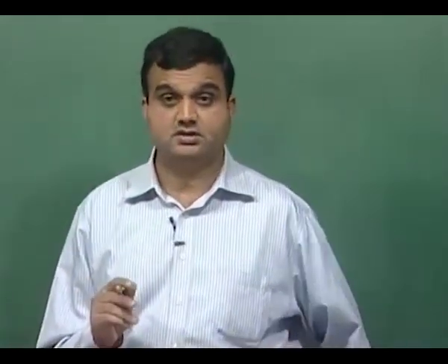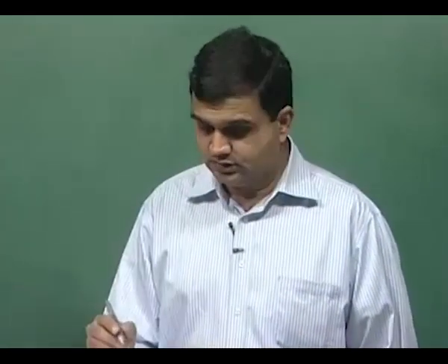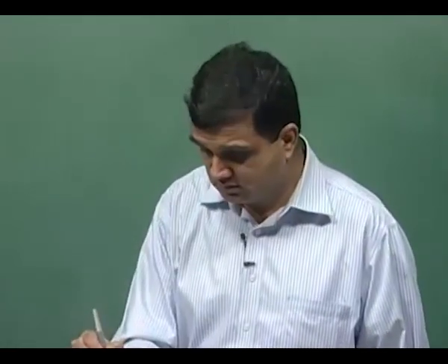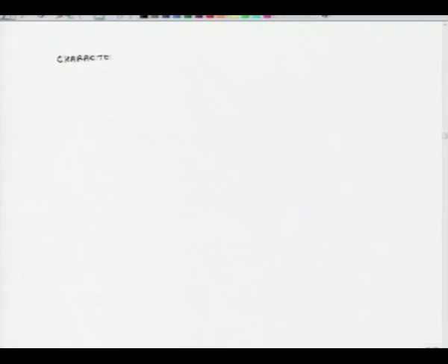I also wanted to introduce a couple of more terms. So, we have talked about characteristic impedance, and characteristic impedance we defined as the magnitudes of P plus over U minus, and that is essentially Z naught, and this is equal to rho naught C, and the value of characteristic impedance is equal to 415 Pascal second per meter for air at 20 degrees centigrade and 1 atmosphere.